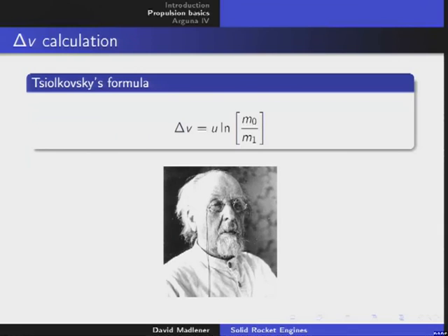So from this equation one gets, first, one should eject mass as fast as possible out of the rocket, so the rocket gets fast. And second, one should get a mass ratio as high as possible. That is, make the rocket mainly out of propellant and everything is fine. The problem is that mass ratios above, I don't know, 10 or so are nearly impossible to make because, for example, for our rocket motor, you need something to hold the propellant during burning. If it has 70 bars, I cannot take alufoil with 0.1 millimeters. It will not work. So in this case, this is a steel casing with, I think, 1 to 1.5 millimeters, and it can barely withstand the 70 bars.